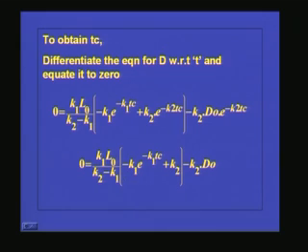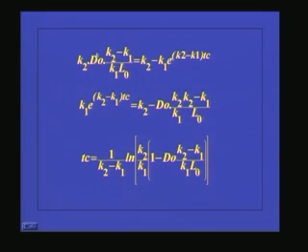So we are differentiating it and equating it to 0. So you will get tc is equal to 1 by (K2 minus K1) into ln of K2 by K1 into [1 minus D0 into (K2 minus K1) by (K1 L0)]. The time can be calculated based upon the K1 value, K2 value, D0 value and L0 value. All these values are known to us, so we can find out the Tc, or the critical time at which the minimum dissolved oxygen concentration can occur in the stream.